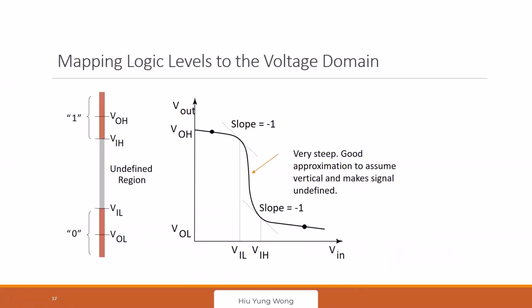You can ask anytime, right? So slope, what is this? What is the meaning of slope? Partial V out over partial V in. Looks fancy, but after all, you're just saying that this slope equals -1. We have 2 points. One is VIL, one is VIH, meaning V input high and V input low. So what's so special here? I don't say it yet, but why is it special?